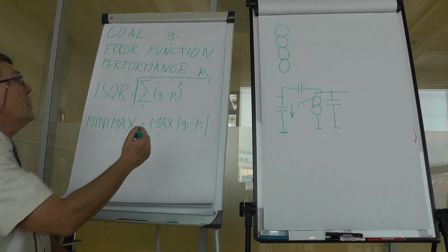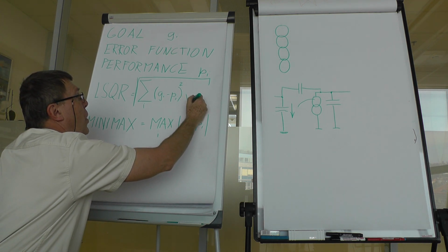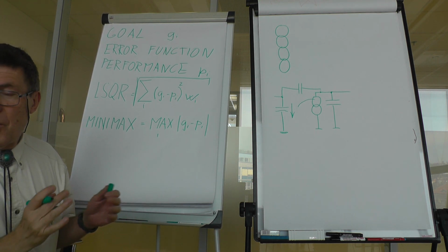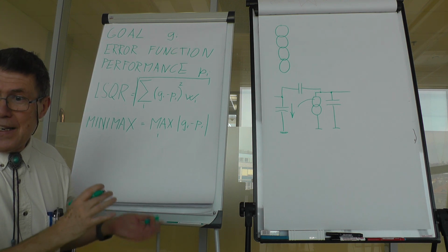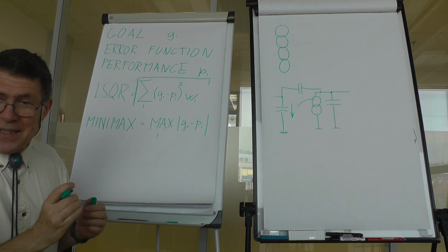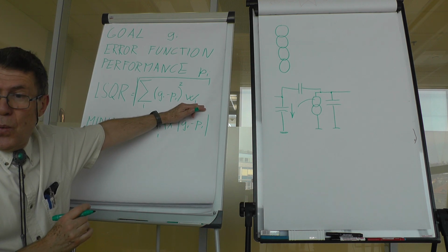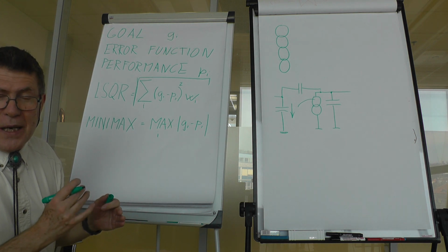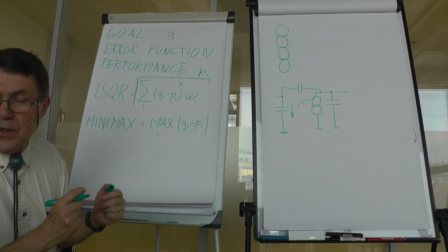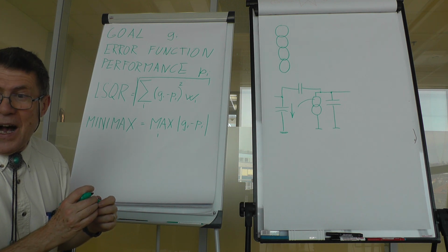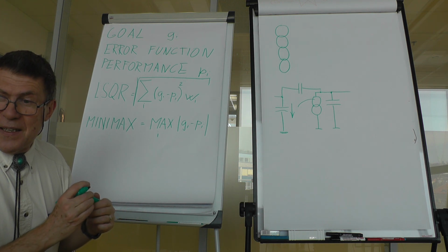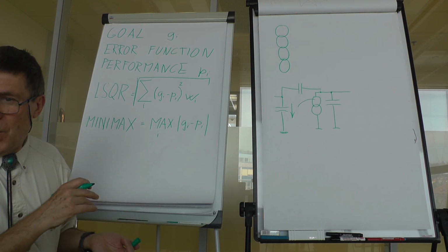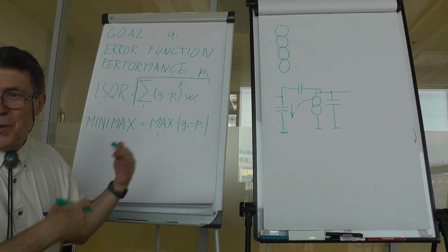And that's why all those functions have one more important point, and that's a weight. So each goal has a weight. Some of them are more important. Classically, if you do not specify anything, the weight is set to 1 for all goals. But in most of the optimizers, you can somehow stress the goal by setting higher weight to that single goal or quantity. And of course, if you set a negative weight, you do just the opposite.